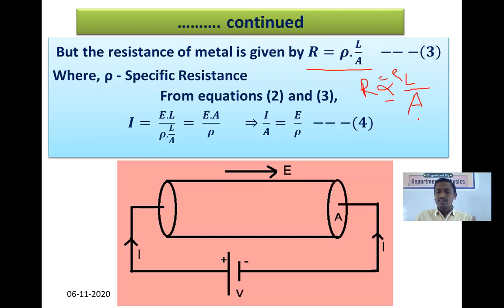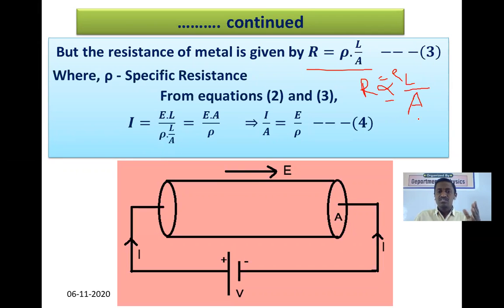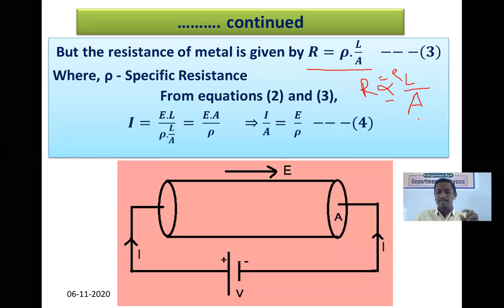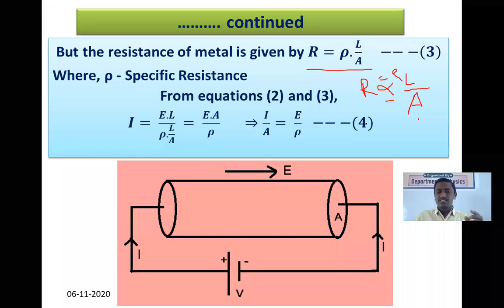Therefore in domestic appliances where high power is required, we use thick wire. Whenever less power consumption is needed, we use thin wires, because broad wires have more cross sectional area and offer less resistance.